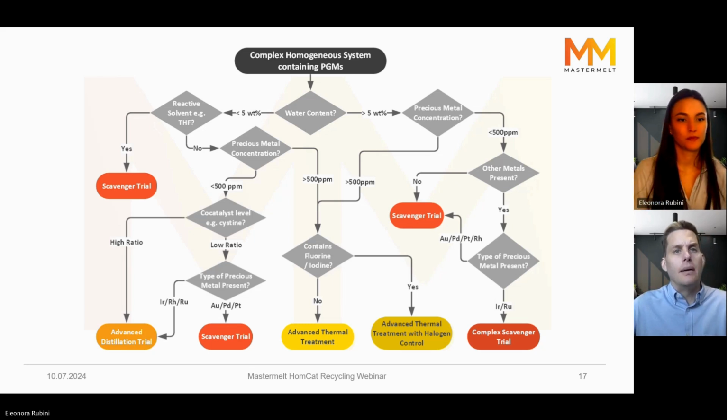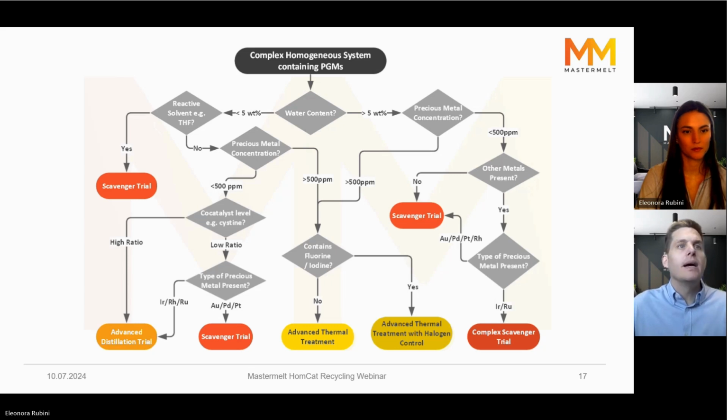And here we'll introduce a number of different scavengers, various different processing parameters, and look at which has the best recovery over time, and the quantity that is recovered in that time frame, to see where the optimum level is. We don't want to be over-processing the material to chase those final few grams of palladium, so we have to look at it and analyze where the right time to stop the processing is.